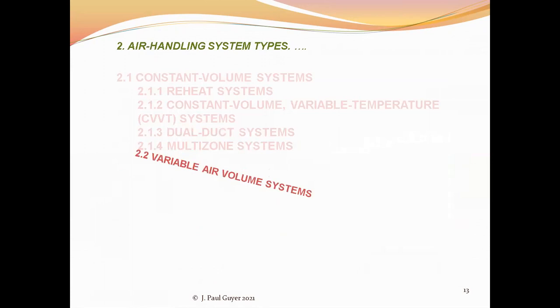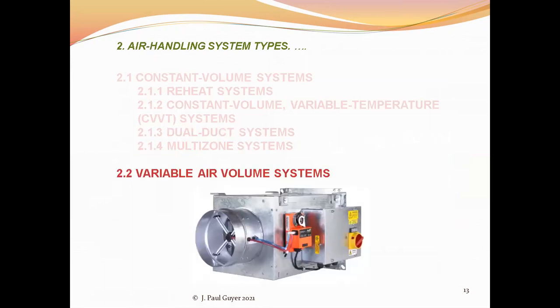And then the VAV systems, which are the state of the art, if you will, these days, rely upon a VAV control box that looks kind of like what you see here. And the thermostat tells that VAV control box, give me some more air in this space because it's getting too warm, or cut down on the amount of air that you're providing in this space because it's getting too cold.